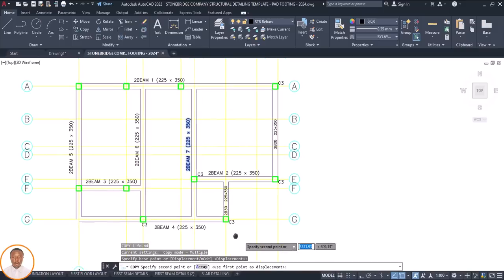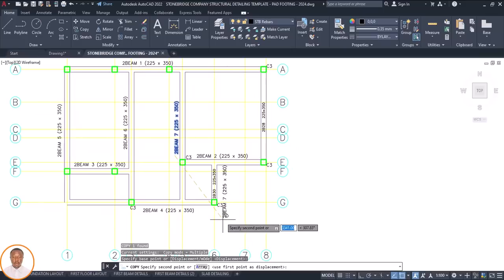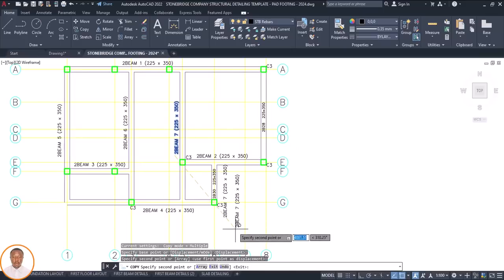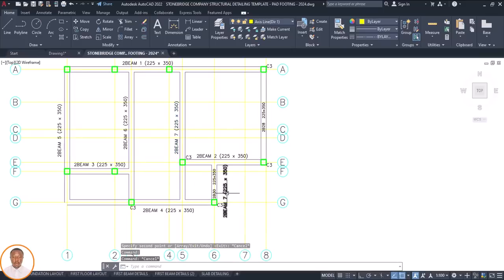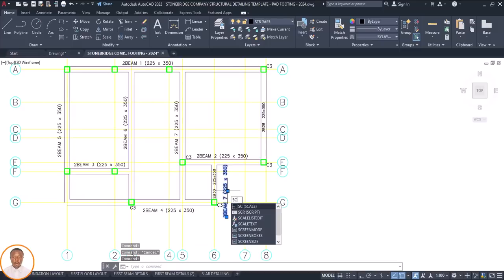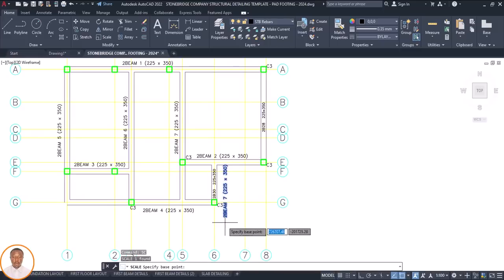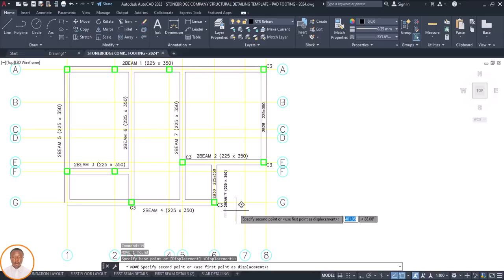It's on this. Second to the last. It's on what? It's on this. Is that okay? So if I like, I'll click on it. Understand? Sorry. I'll click on this to reduce it. Then there's SC, which stands for scale, enter. So at this edge here, 0.7, enter. So you can see I can reduce it. Is that okay? So M, enter. So that's move.